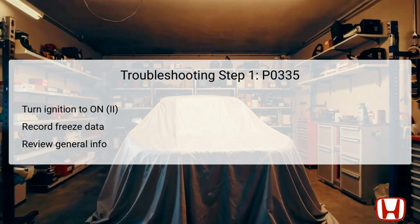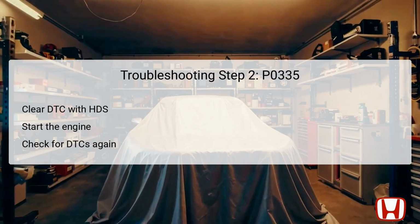Let's proceed to the next step. In step 2 of the troubleshooting process, we utilize the Honda Diagnostic System, HDS, to clear the DTC. Following the deletion, the engine should be started to see if the DTC reappears. This step serves to reset any temporary faults and gives us a fresh start for diagnosis.